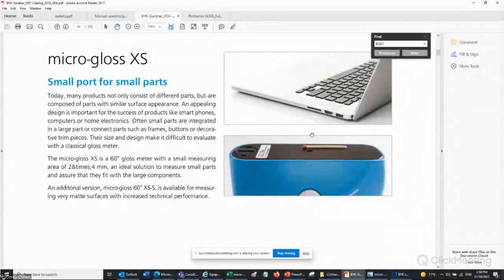So yeah, I find it easier, and I do this with color meters too, with spectrophotometers. If the part I'm measuring isn't much bigger than the aperture opening, I find it easier to just turn the meter upside down and lay whatever I'm measuring on top of it, rather than trying to place the meter on top of a very small object and center it perfectly.